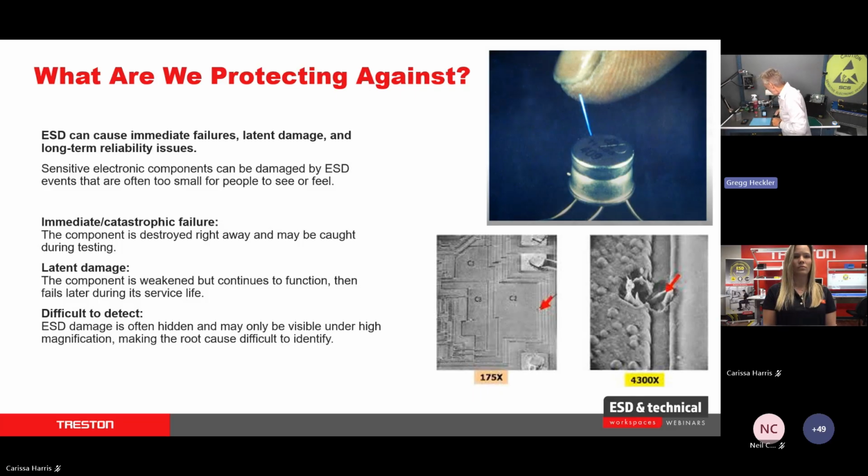Also, just so you know, it's very important to understand, and this confuses a lot of people: the only time you can have these significant events is when one charged conductor touches another conductor. So me touching the doorknob, or what we call an HBM event, I walk over with a charge on my finger and I touch the lead of that IC. That IC is not only conductive, it's at a lower potential than I am. It's much more conductive than I am. My body's about 500,000 ohms, that lead's 0 ohms. So that's how we create events in general.